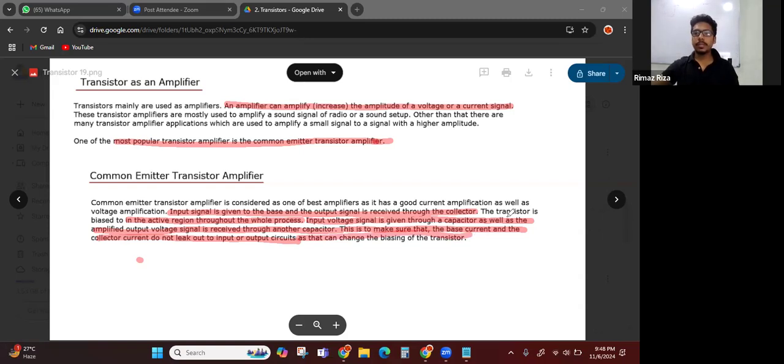Okay, so always remember, in a transistor as a switch, off means the BE junction is not biased, the cutoff region. Switch on means it's fully biased and then saturated. In an amplifier, we use the whole process in the active region.